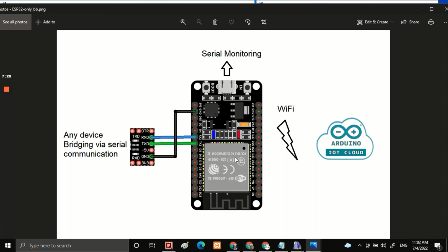This scenario will be very important when we are collecting data from devices, from sensors, and from communication modules such as LoRa or GSM that we read over serial. We are able to collect the data and process it, do further coding, and send it to an IoT platform. One important thing is that we are able to read serials at the same time.